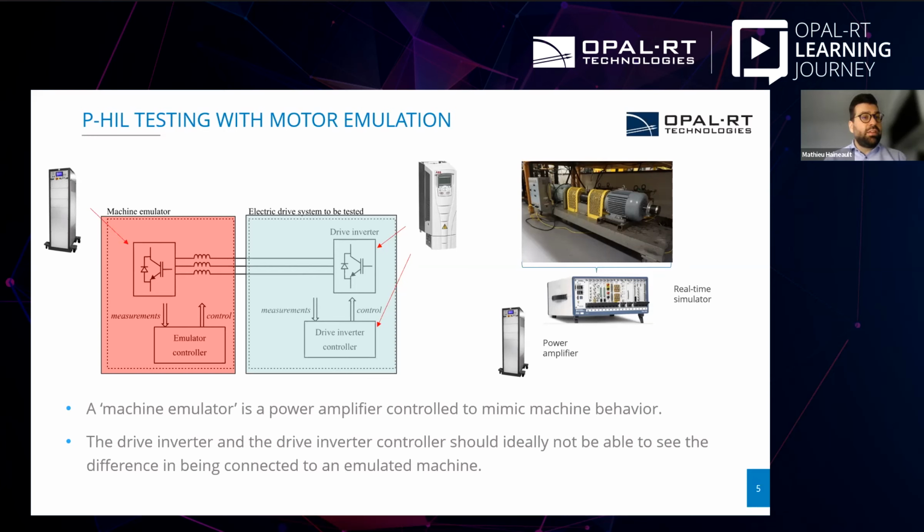For example, changing from one topology to another is just connecting the three-phase machine inverters, and we can change the topology of the machine on the fly. An application we had with customers is that they want to test a broader scope of different motor impedances for a single drive. With the emulators, we can sweep the impedance of the motors virtually and have the same behaviors as a real machine without any mechanical or physical changes to the systems.